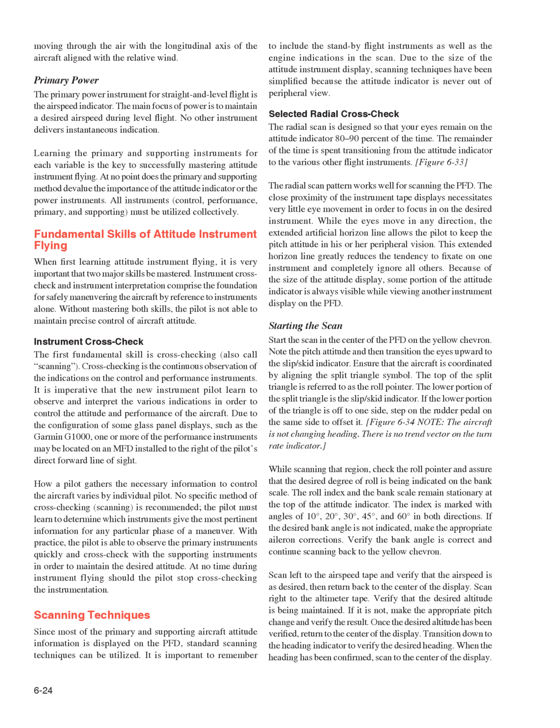The pilot must learn to determine which instruments give the most pertinent information for any particular phase of a maneuver. With practice, the pilot is able to observe the primary instruments quickly and crosscheck with the supporting instruments in order to maintain the desired attitude.